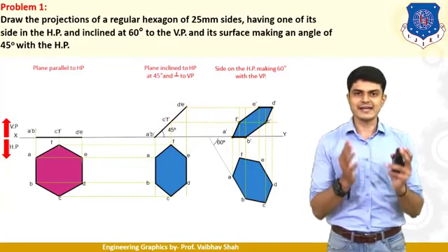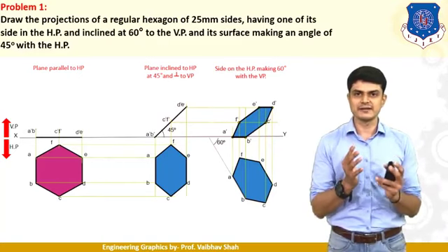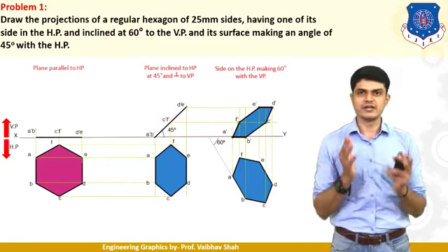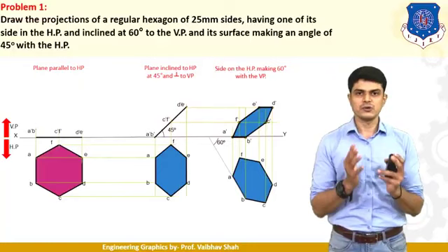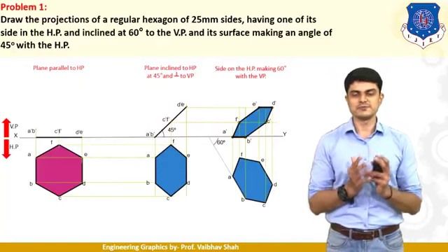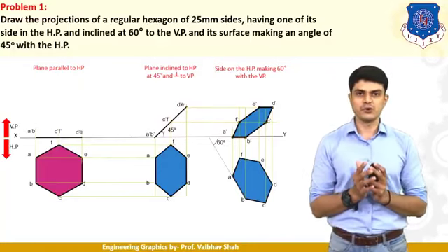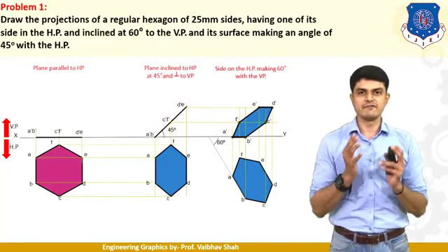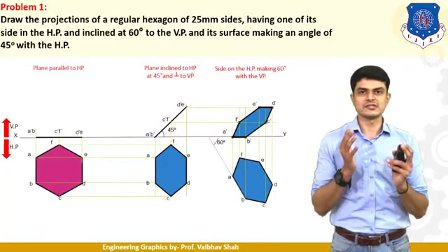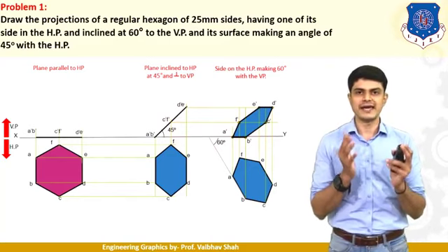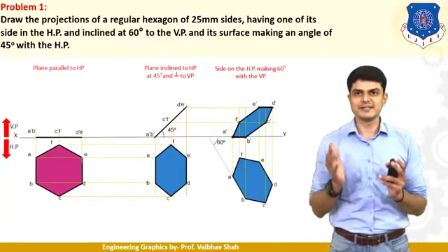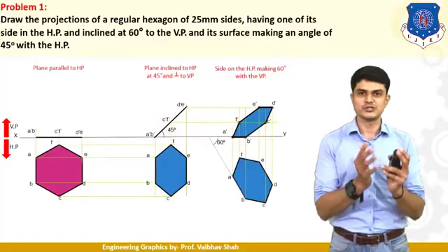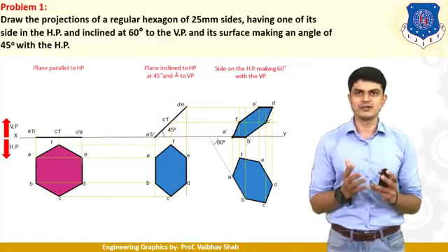When you connect these 6 points, you will be having this hexagon like I have drawn. After getting this hexagon, let us give the numbering pattern A, B, C, D, E, F in the anti-clockwise direction. So our top view is drawn in HP. After getting this top view drawn, we should draw vertical lines from each and every point of your hexagon, and we will be having one horizontal line as a front view in VP on the XY line, as you can see. So A dash, B dash, C dash, F dash, and D dash, E dash. Then after, in the next stage, what is said?